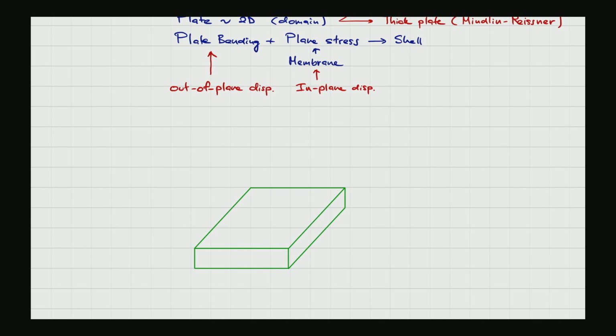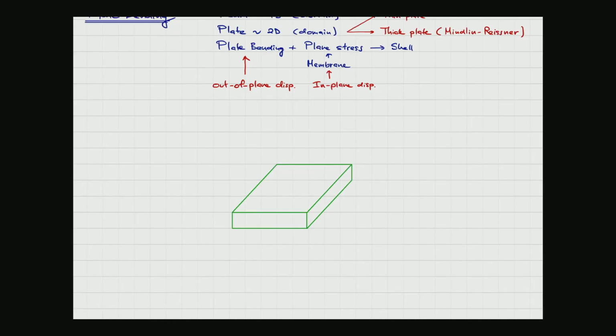For a transfer girder, that depends as well, but it is not as brutal as the pile cap, because the pile cap is very thick, and we generally expect very high stiffness from the pile cap.